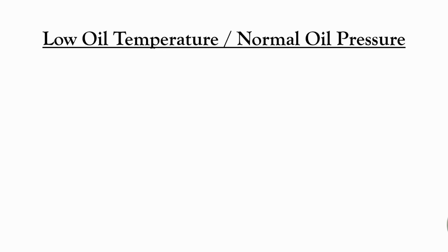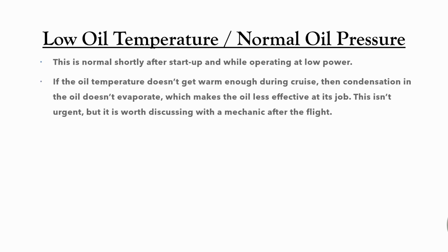First, let's consider a low oil temperature with a normal oil pressure. This is the normal condition right after you start up and while you're operating at low power. It takes a little while for the oil temperature to come up into its normal range. If the oil temperature doesn't get warm enough, even during cruise, then condensation in the oil won't be evaporating and leaving the oil. That makes the oil less effective. That's not an urgent situation, but it is something that's worth discussing with your mechanic after the flight.